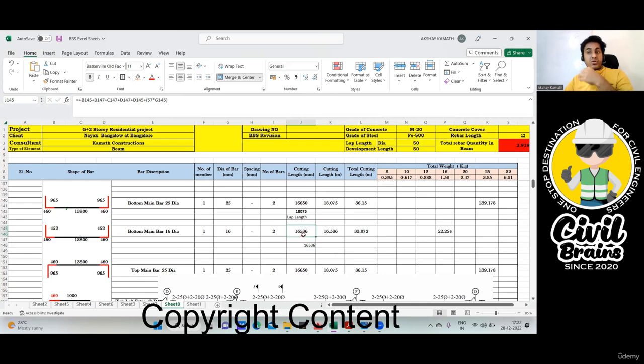And if you find it greater than 12 meter, add one lap length. For that, suppose for example your length came out to be 30,500. How many laps will you put? In that case, it's not one lap length. You have to find the number of laps. 30,500 divided by 12, you should do. How much will you get?